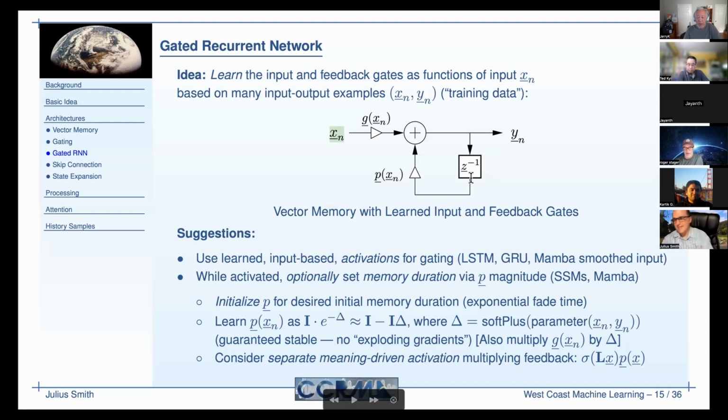Maybe we can move on to where we're trying to get to, a little bit further down, if you don't mind. Don't push me too hard on the signal processing interpretation here in the Z-plane because it is not an option. Although this is really just a delay, and a delay really does have a Z transform, we can't compute the Z transform. We can't compute our transfer function because we have a nonlinear system. There's no such thing as a transfer function here. There's no such thing as a frequency response unless you want to tabulate it for every possible input.